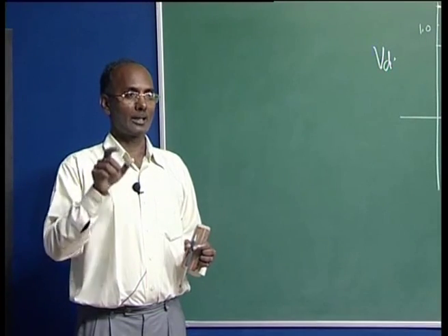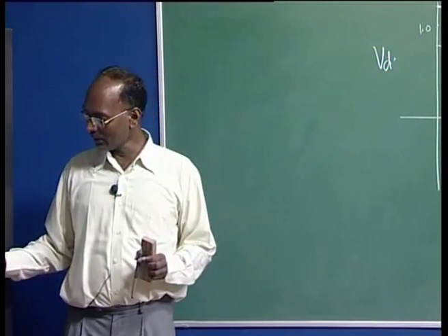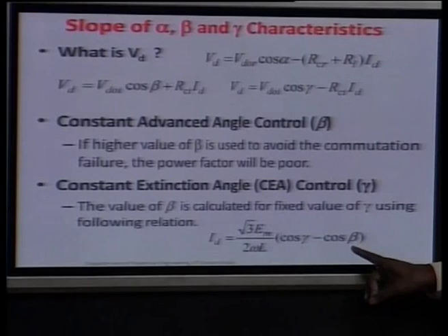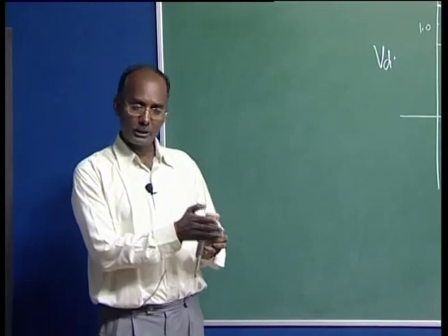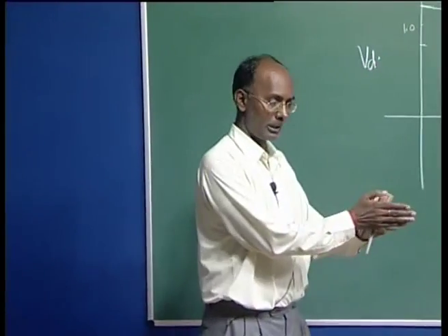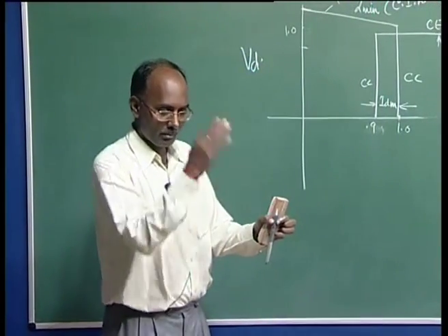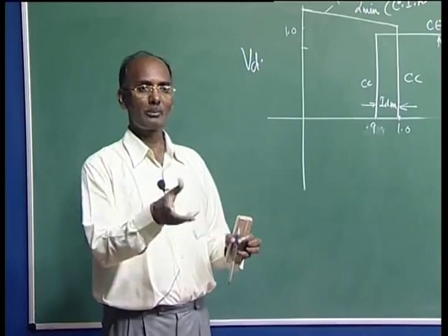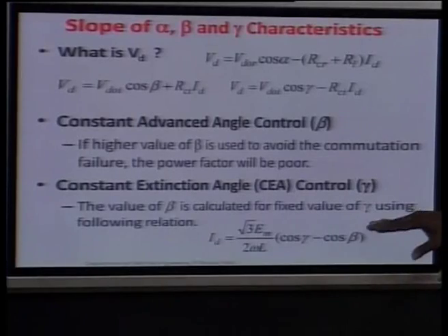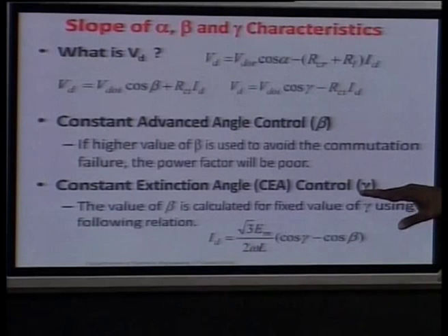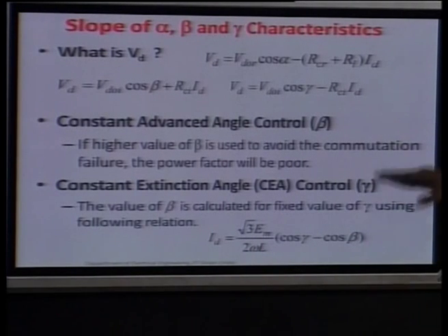But there is also a possibility: once you compute this beta and then a voltage dip occurs, because you computed the values based on the previous instant, once you fire, the voltage has dropped and then the commutation angle again increases. So it is also not 100% assured by the gamma control. There is some risk, but still that risk is less than the other risk.